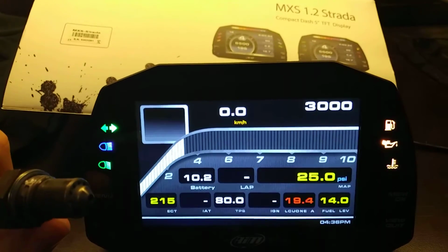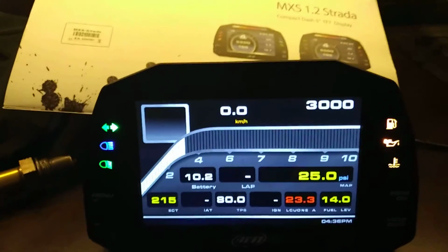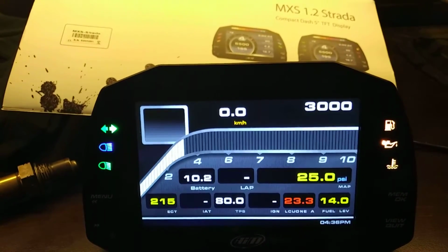And now we're back up to free air. So we can also just simulate the LCU1 number. So let's say we force it to be 12.5 AFR. You can see there that the warning turns yellow, and then if it's rich, so we can change this value to be, let's say, 11, which would be allowable under full load, the warning goes away.